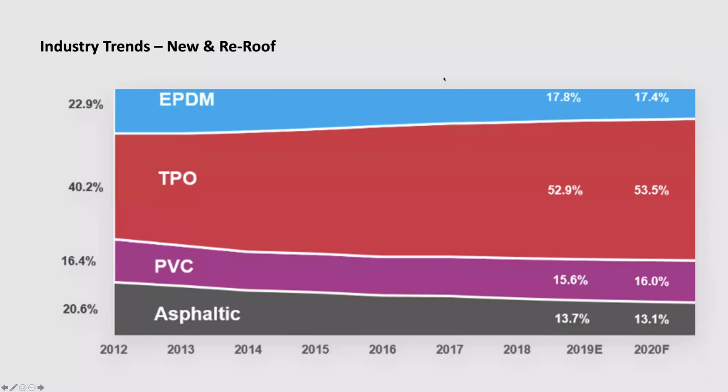We'll send you back with a little commercial roofing industry knowledge here and kind of how this breaks up. I had mentioned that TPOs are the king right now of low slope commercial roofing. They've eaten away at their friends, the asphaltic and EPDM roofs. If we were to have a chart like this going back 10 years, you'd see that the EPDM and asphaltic really dominated, and TPO slowly made a climb, while PVCs have held their own, generally because of the fundamental things that naturally come with those, the contaminant and grease and animal fat resistance. So there's some industry knowledge for you.